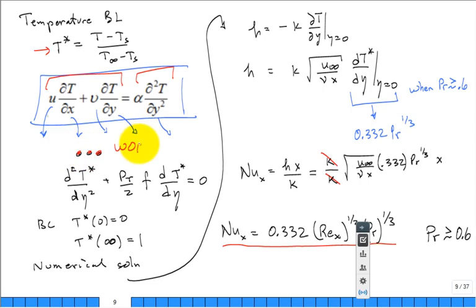a lot of work, because you've got to take that solution for U with that similarity in the stream function, and then you have dT/dx and all that, and you work it out and you find a new ordinary differential equation where you're now bringing in U, the solution of the velocity field, into it, and there it is. Let's take a look.